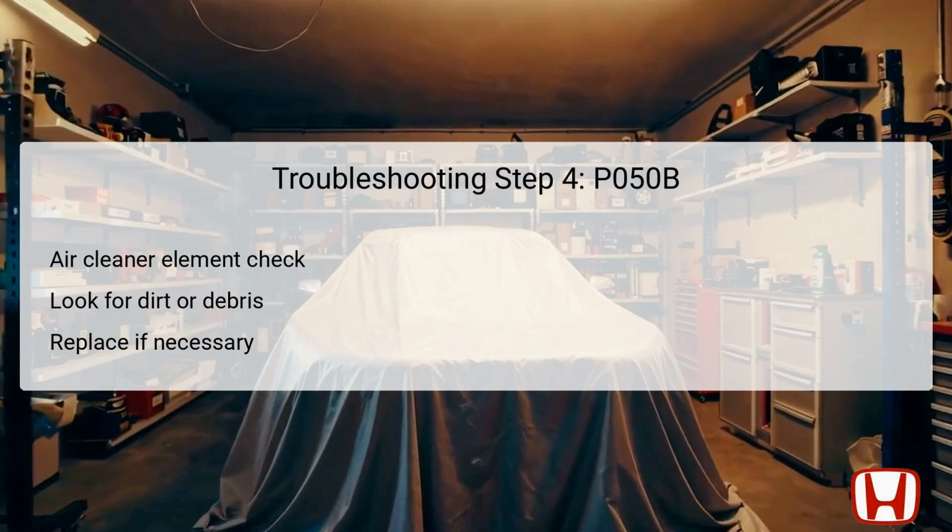If the element is found to be contaminated, it is essential to replace it with a new one to ensure that the engine receives sufficient clean air. A well-maintained air cleaner element is critical for maintaining engine performance and efficiency, especially during cold starts.